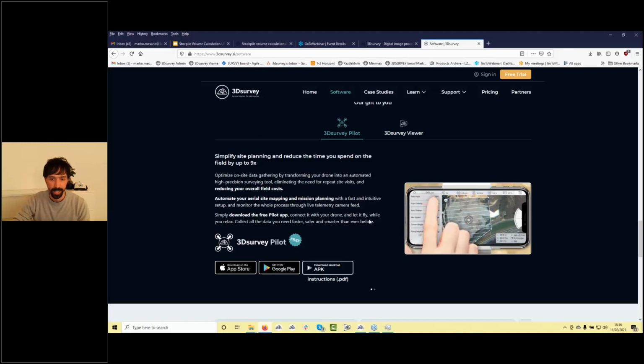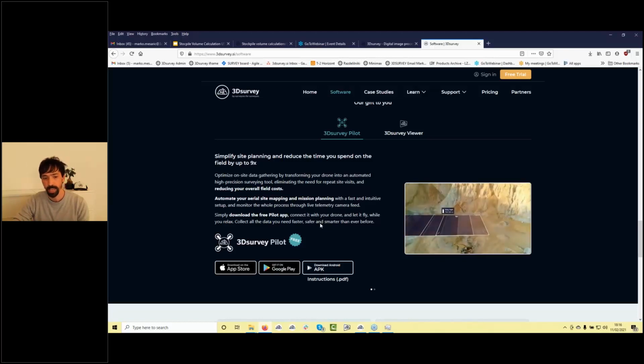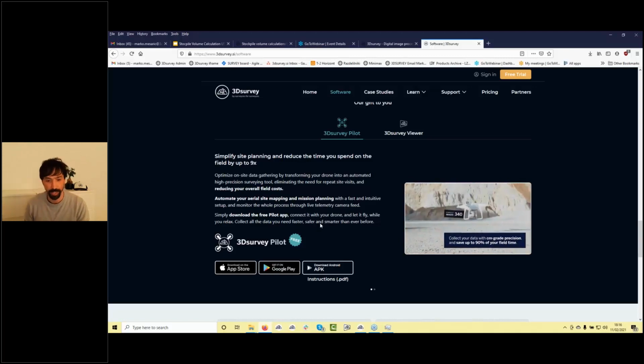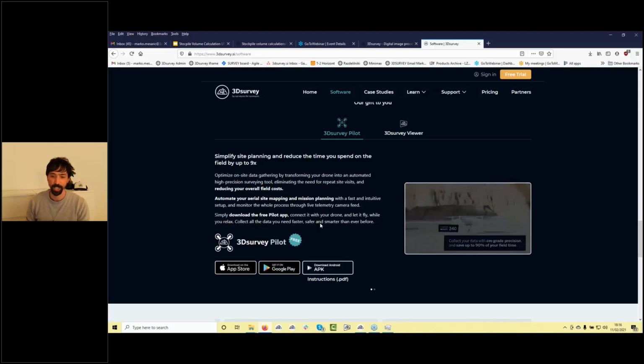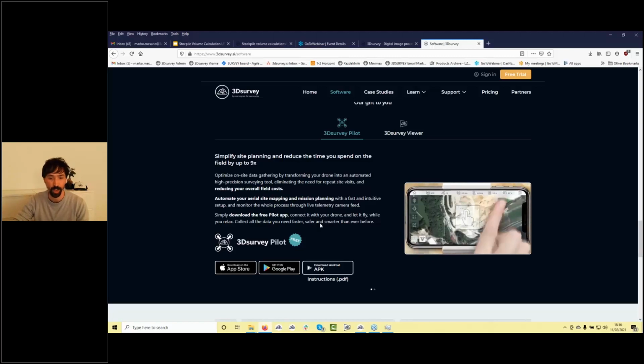Okay, and then the last question from Slovenia. Do you expect improvements in battery quality, working time? We use the Phantom 4 RTK. Not sure, it's more a drone question. So the flying time for drones currently, I think 25 minutes is realistic. By the papers, it's 30 minutes, something like that. But I would suggest buying additional batteries when we do big projects. We have 10 batteries in a pack and you can easily map more than 10 kilometers of road in a single day.